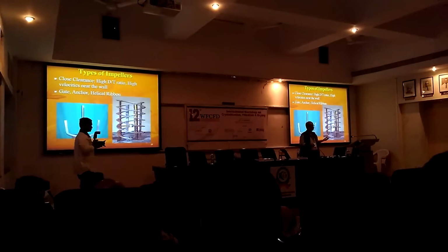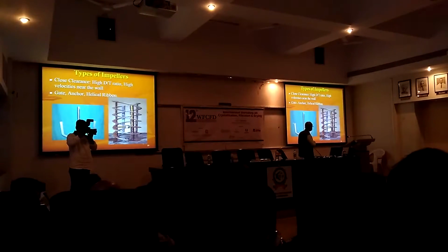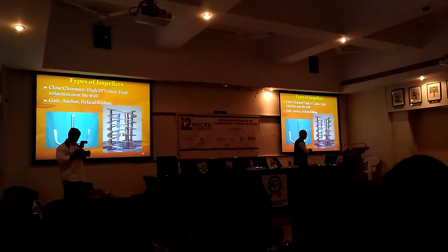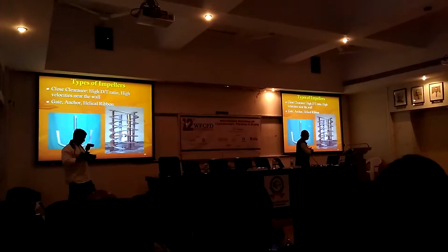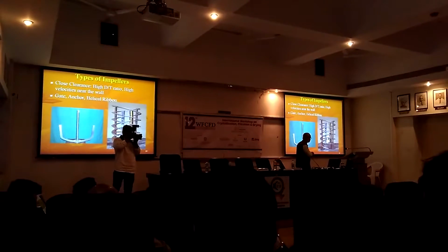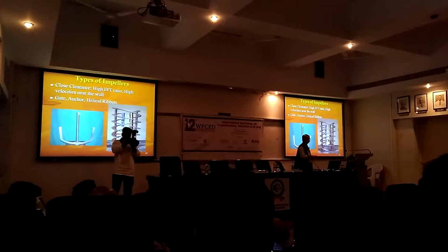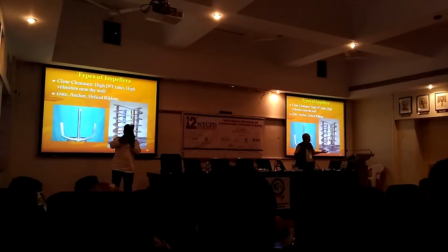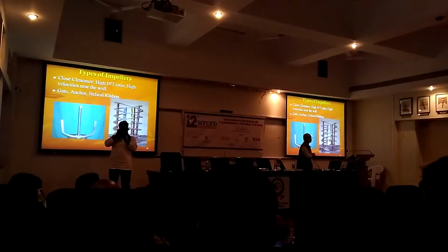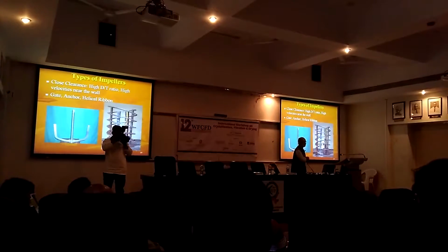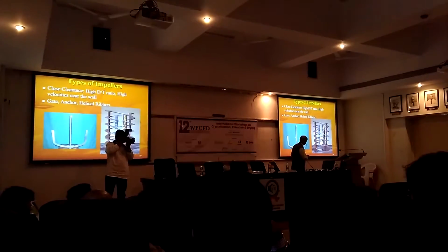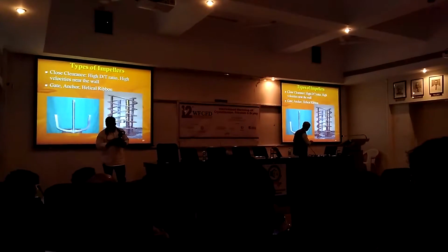The simple reason for that is when you start the process of crystallization, the liquid level is up to here. When you carry out evaporation, the liquid level reduces. If you happen to have an impeller located out here, and if the liquid level goes below that, what do you do? You can't do anything. As a result, when you compromise, this is probably the worst kind of impeller which you can use ever. Right? Never use this.